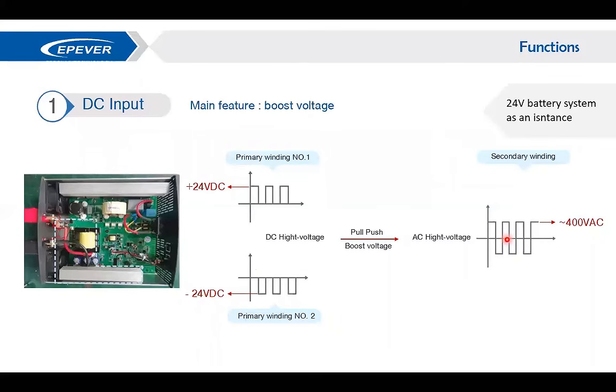And there are some MOSFETs, as you can see, and some fuses here. Heating components are bolted onto a heat sink here for thermal cooling. And iPower really has a good thermal design. And here are some capacitors, a transformer, a heat sink, and input cables, and so on. So this part takes care of converting the DC input to an AC output.